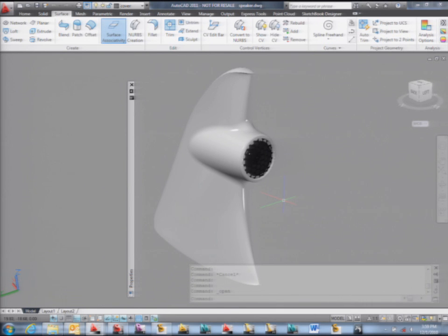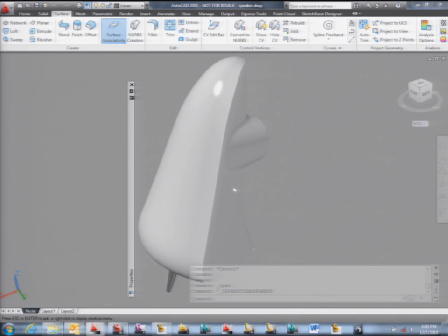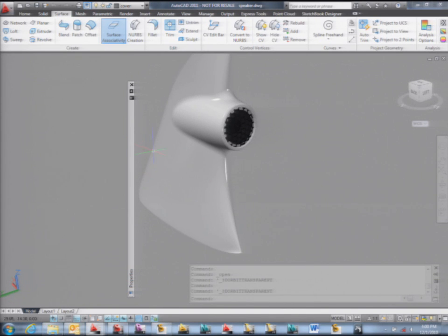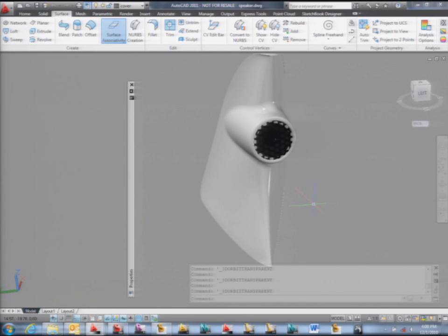So I created the base. From the back of this became one surface, right? There was a loft between three sections and two guides here and here. Then I made a patch that basically closed this. I made a circle in front of it. I just extruded it back, and I trimmed it and made a fillet between both surfaces. Done.